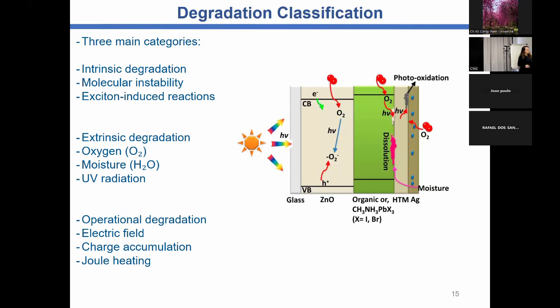For instance, take solar cells using zinc oxide. Zinc oxide has a catalytic property. It has been observed that zinc oxide can increase the degradation because of its catalytic property with oxygen inside the organics. So depending on the application, it is not so desirable, even though zinc oxide is quite an important material as ETL.